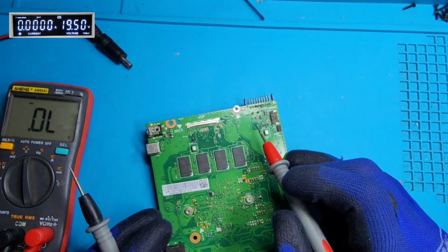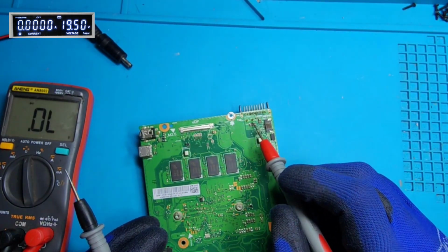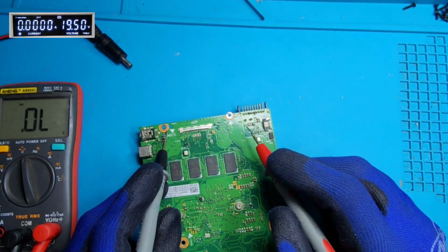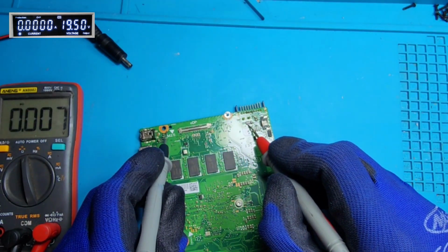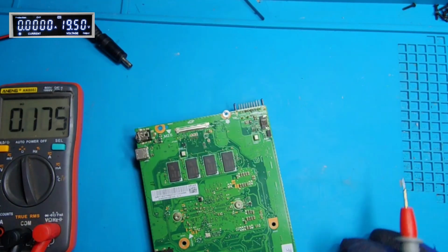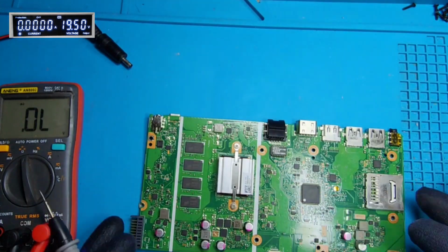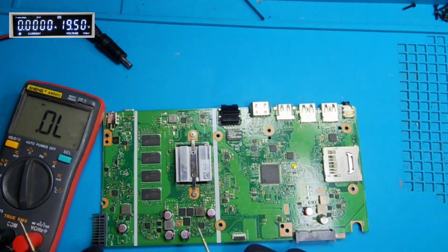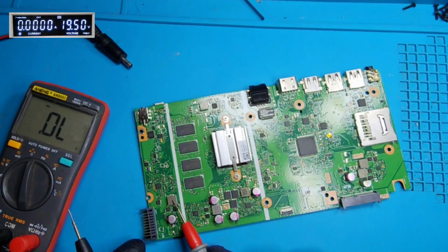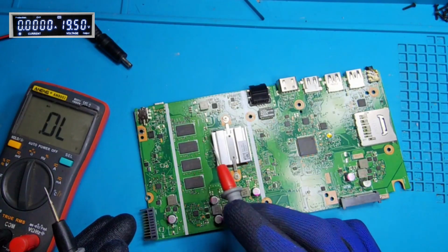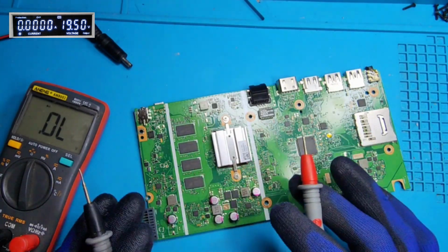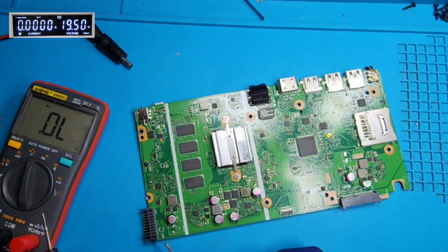Okay, here we have the current sense resistor of the battery, and yeah, it is also shorted. Okay, yes. So up to now we have high impedance on all the coils except the battery coil. So injecting the voltage will not kill anything like CPU or EC chip or anything on this motherboard here except this battery section.